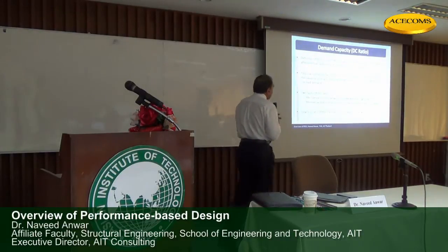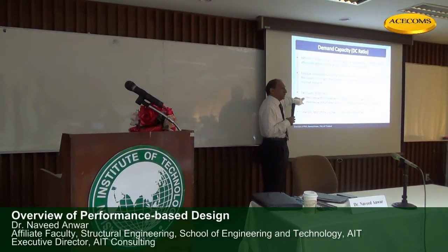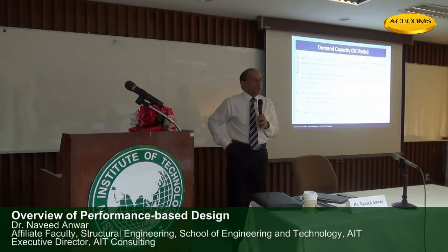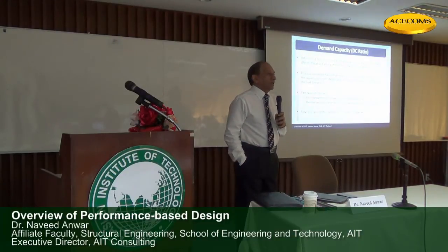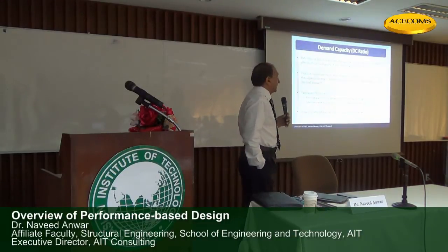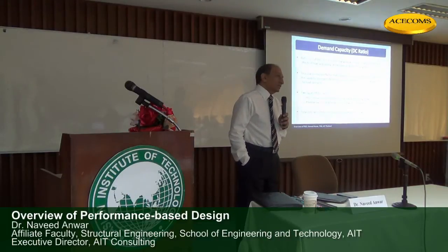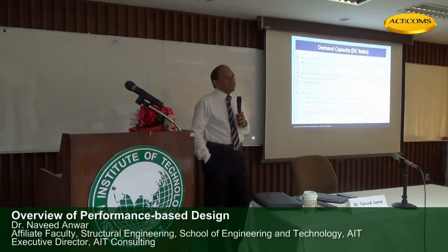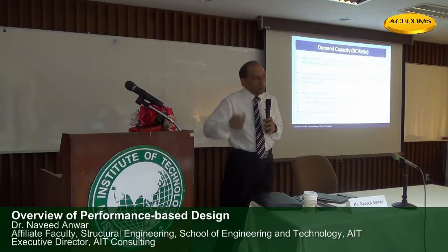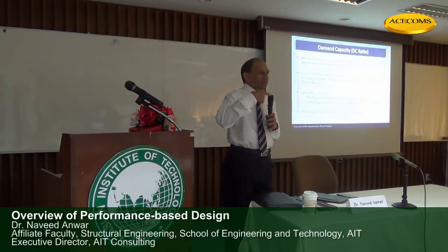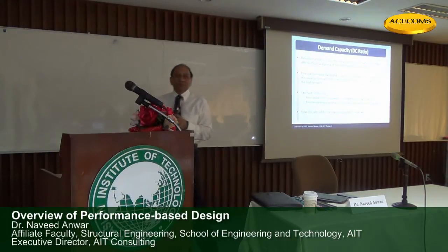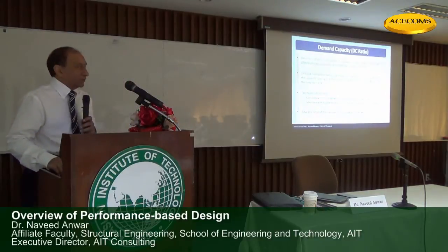But this combination of these DC ratio gives us now new ideas to design the structures, because some members we can design as force controlled or based on the brittle concept, and some members we can design based on the ductile concept. Up to us now, we can decide what we want to do, right? So gradually we will move from force conventional design to capacity-based design.